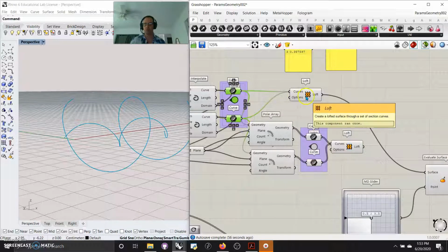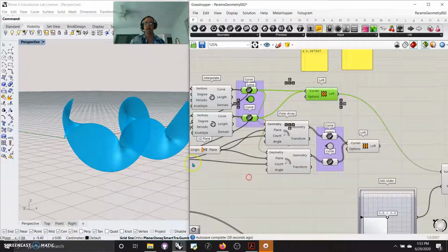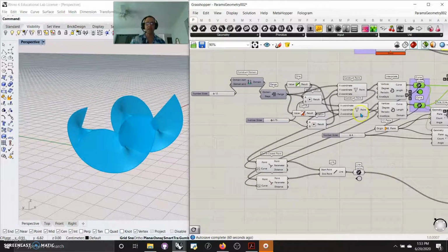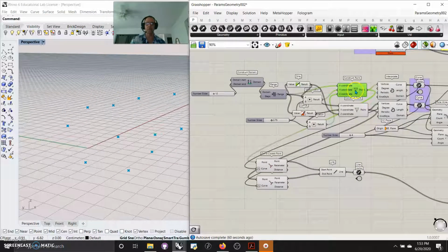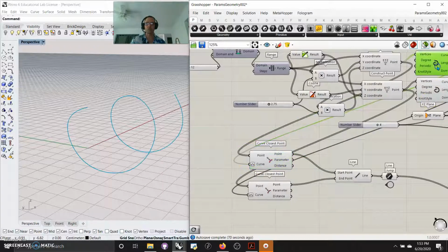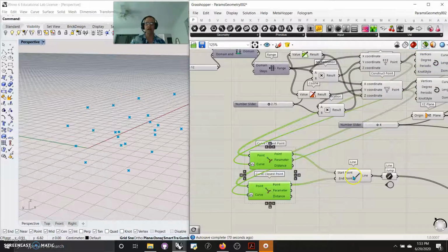These two lines lofted, do that. And look at that geometry. I want you to see a different take on this. If I take these set of points, if I shake this down, the points, and I go to a curve closest point, and I take a reparameterized curve from that interpolated curve, and I switch them up on two separate curves, this one and this one, and I draw lines between them, I have all these lines.